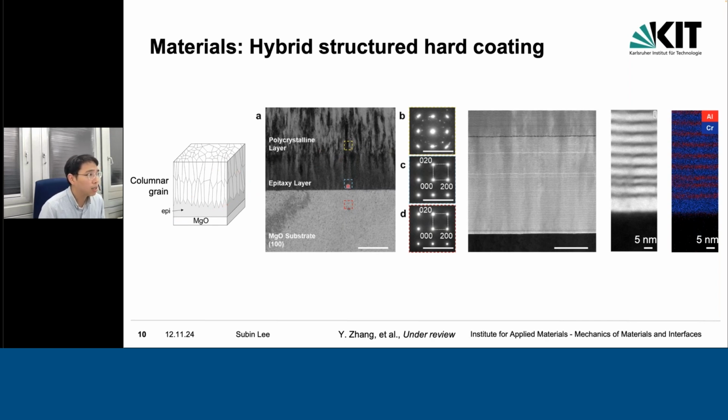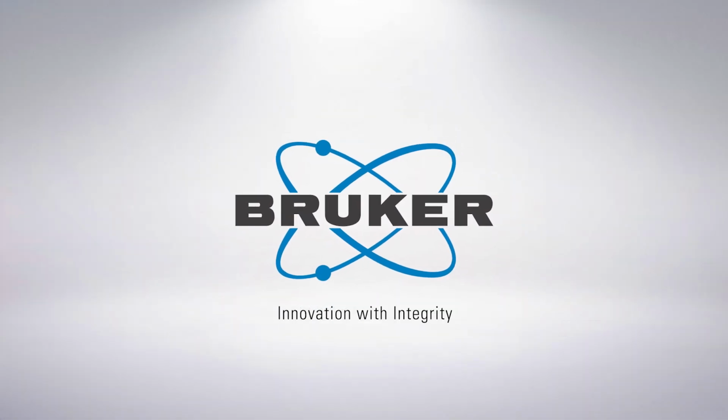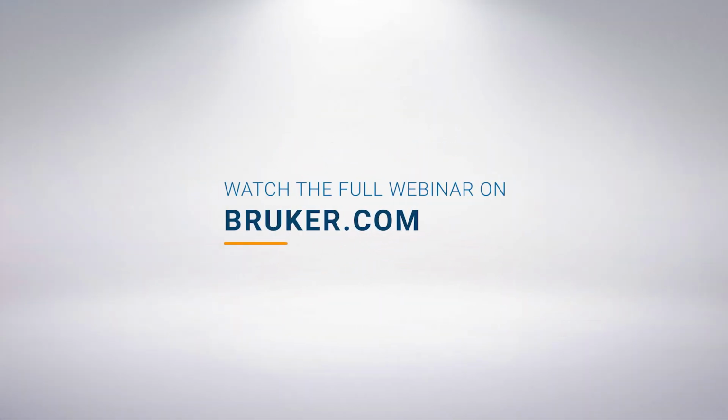As you can see in the TEM image, this is the MgO substrate, and there's the epitaxial layer, and on top of it there's a polycrystalline or columnar grain structure. This STEM HAADF image and EDS images show the multilayer of alternating chromium nitride and aluminum nitride layers. The total thickness of the samples was around 1.8 to 2 micrometers. Then we prepared micro cantilevers using focused ion beam, and they look like this.